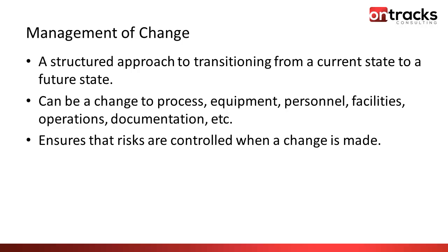Management of change should also include assigning personnel, and that can be to either approval or to various tasks involved with the MOC. An MOC should also include a process for tracking action items. It should also include, towards the end of it, training of any personnel that might be impacted by the change, and any safety information and documentation should be updated per the change.